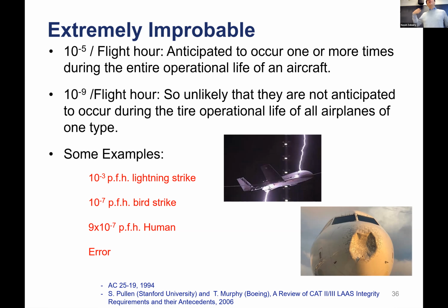So one time, one of the aircraft out of thousands in the 40 years might experience this type of load. And then you don't design the aircraft for that load. But that means that one of the aircraft might fail because of a load that you haven't designed it for. And you accept that. That's where the line is. That's why I'm saying it's a bit unsettling, the reason behind why we choose these lines. So we design it such that one aircraft might fail, but beyond that, it's not economical, basically.